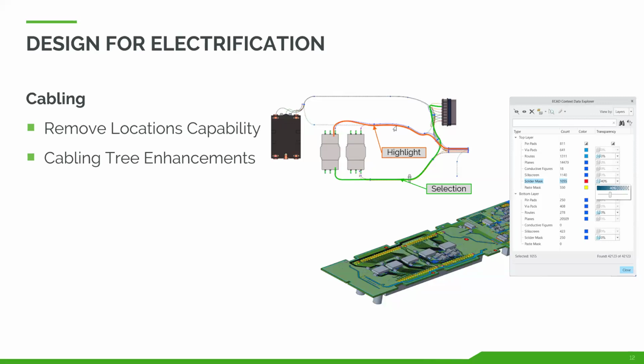In Creo 10, we introduced that notion of having a cabling tree inside of Creo to manage all of your different cables. And in Creo 11, we've added additional capabilities, mainly around filtering and going through that table. And then there are some productivity enhancements with cabling, mainly around visibility controls for that cabling tree, and even added support for your cosmetic features, such as having your cable ties not be shown in the cabling tree, so you have better visibility if it's too blurred onto your model.